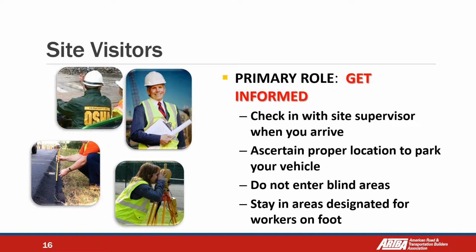First thing, it's very important, okay? Because we have cases in which inspectors arrive to the work zone and start walking in the middle of the area and they have incidents because they are not aware of the dynamics or the rules of the work zone. Maybe he or she is walking in an area only for traffic. Find a certain proper location to park your vehicle.